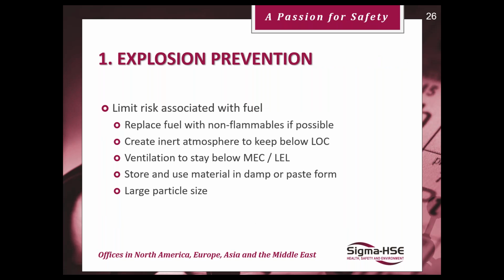Some things are relatively simple if you can change your processes. If we can replace the fuel with a non-flammable one, or a liquid of one flash point with a liquid with a much higher flash point to do our processing operations, inherently we can be safer.